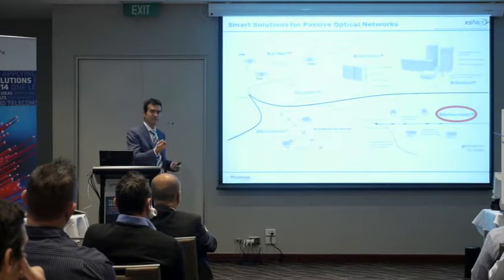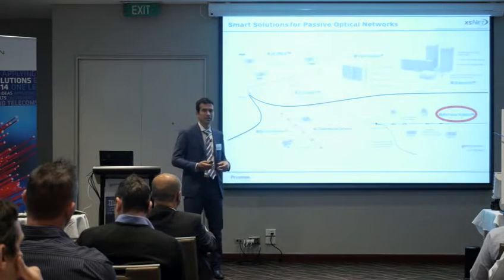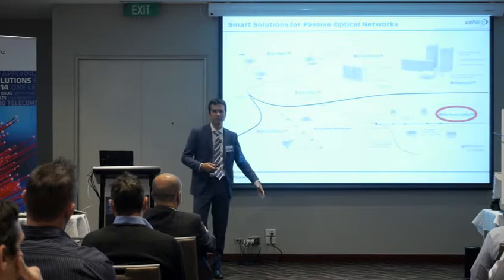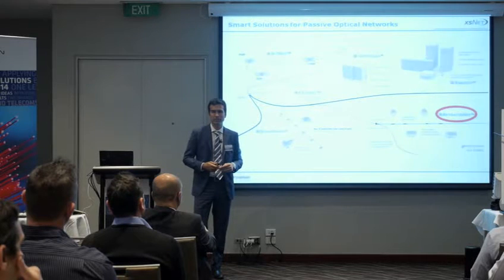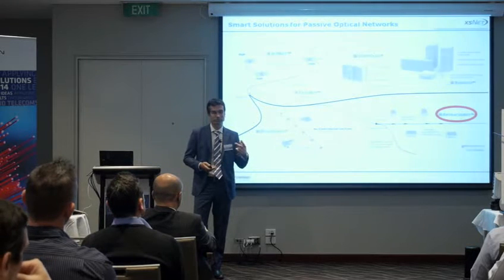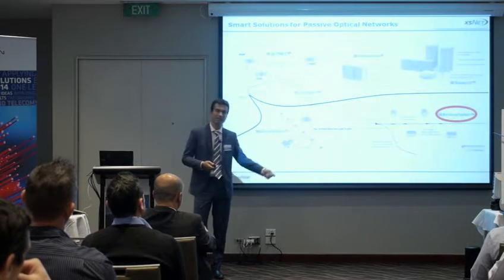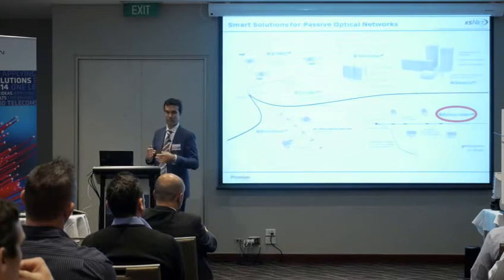Because at the end of the day, the force to be applied is not much. Especially after maybe the first fiber, which can be a bit tighter, but then the second, third, the cable is getting empty. And it's exactly because of this ease of extraction that if you are making a street with single dwelling homes, sometimes you don't really need to open the second window, but you just cut everything and you scrape what you don't need.